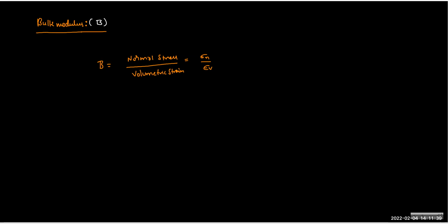And here, the dimension is not very specific, whether it's one-dimensional or two or three. So when we have real world objects, then bulk modulus is the best way to proceed. Okay. For gases, we cannot define Young's modulus. For liquid, we cannot define Young's modulus. For solid, we can define Young's modulus. But bulk is defined for all three cases, solid, liquid, and gases. So for a solid body, the Young's modulus and the bulk modulus will have some relationship. For liquid and gas, because we cannot define it, we have only bulk modulus.